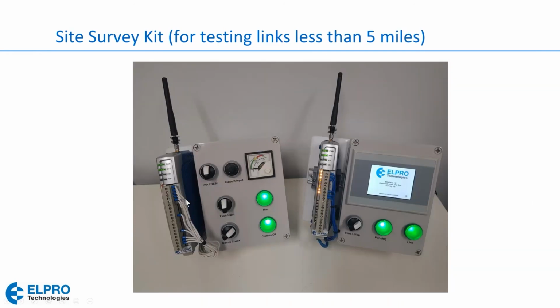And what we do, as soon as we unpack it, we mount the radios on the DIN rail strip that you can see at the back here. We plug in this terminal block, so the whole terminal block just pops out, so you don't have to rewire anything. I would never recommend disconnecting any of these wires, because otherwise you'll have to figure out how it is wired. And there's a power switch in the back. We just turn on the power, and then we're good to go.